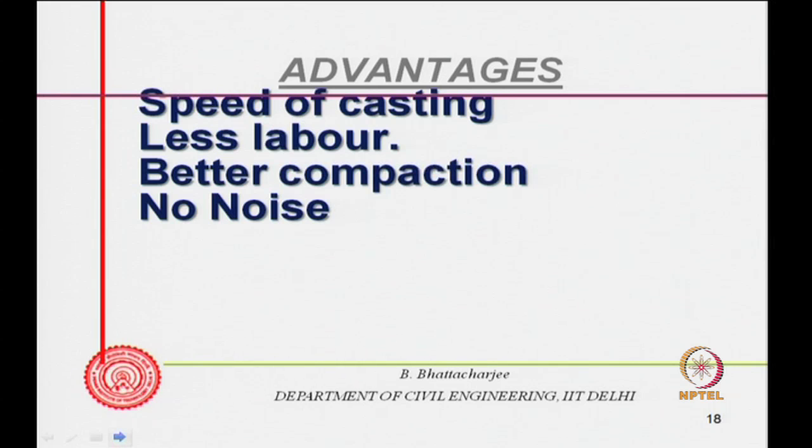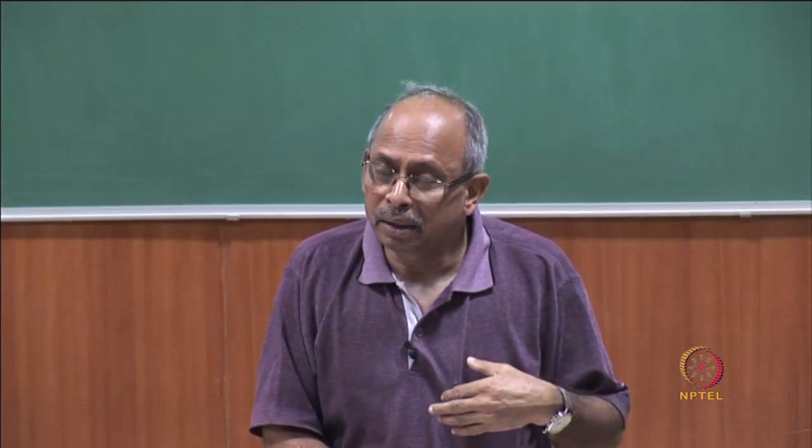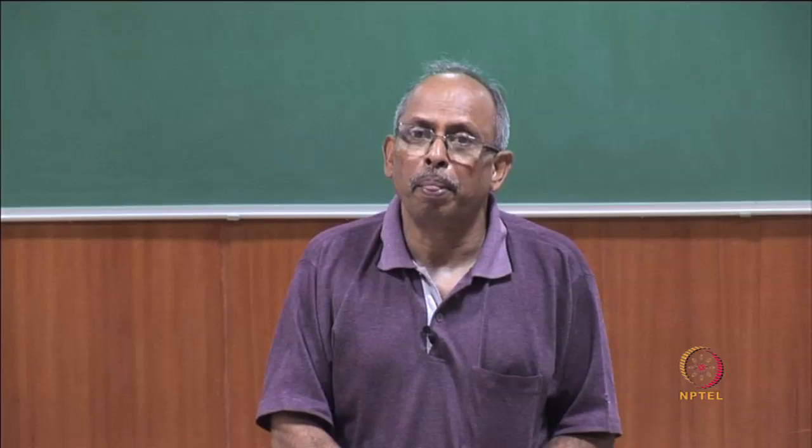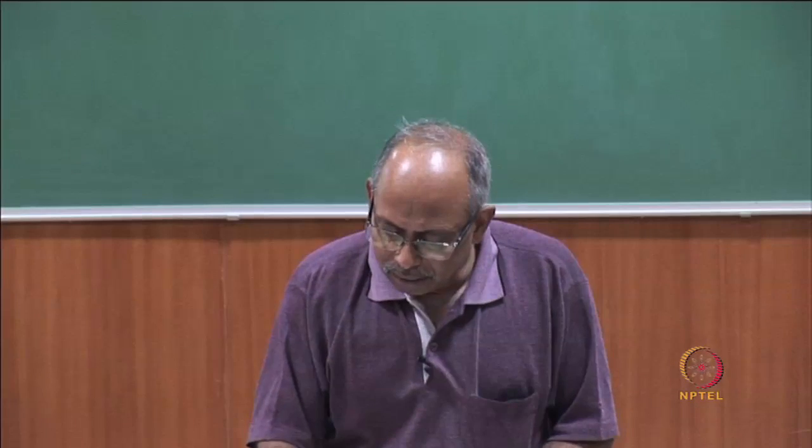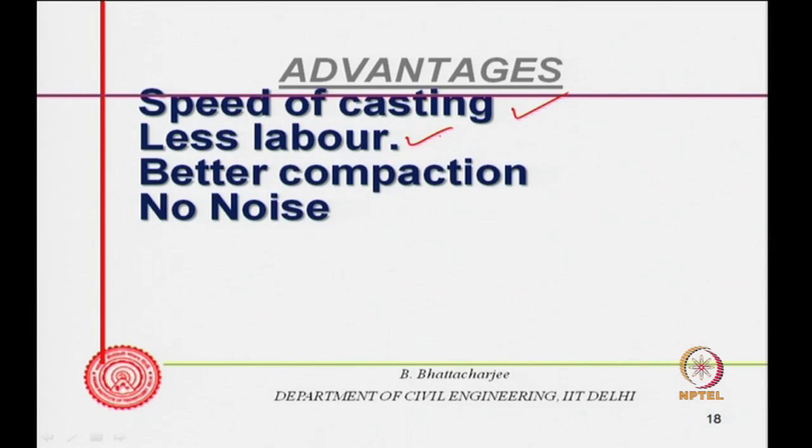So, what are the advantages? The advantage obviously, first, is speed of casting. If it is self compacting, you do not require vibration, so the speed of casting will increase. Less labor is of course an advantage in western countries, because, as I told you, it first came for these two purposes, no noise and less labor, cutting down on the labor cost of vibration.